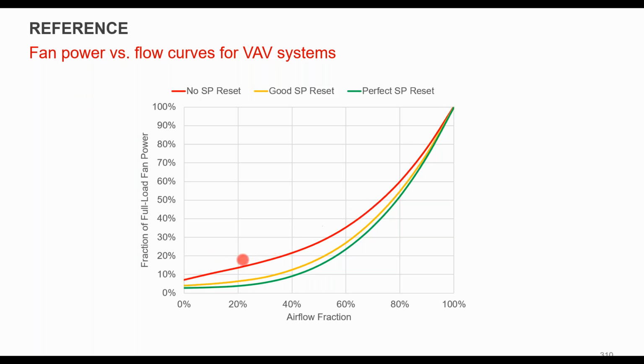That says that if you have a VAV system, that you should unload along that line, right? There could be ways to model static pressure reset as well. Some systems, and some softwares, will actually model pressure within the system. In many cases, you're just going to have to create a separate fan curve that mimics what would happen if you have a pressure reset system.